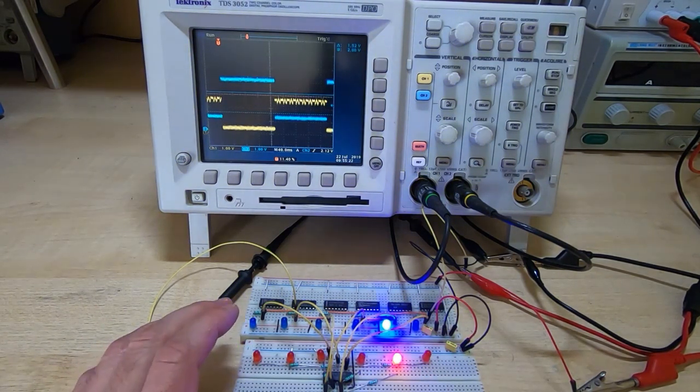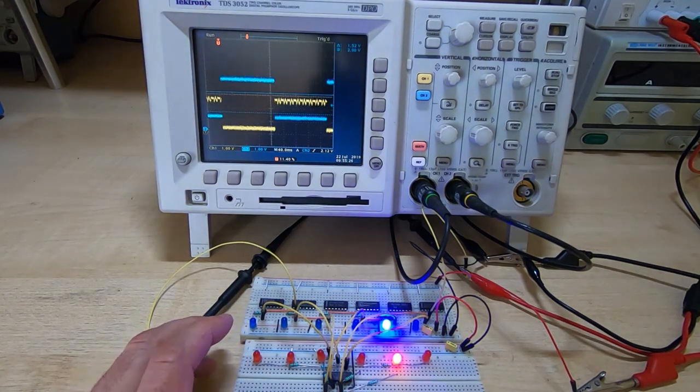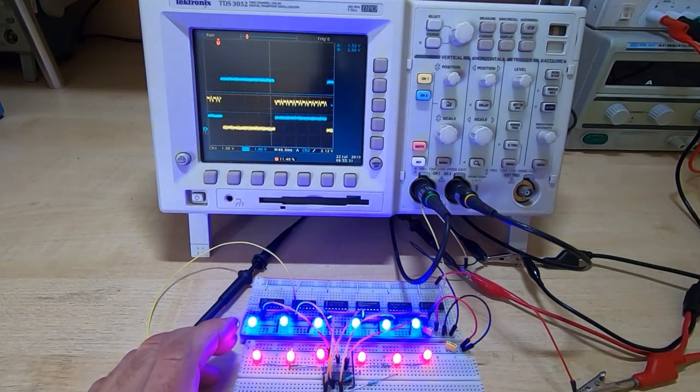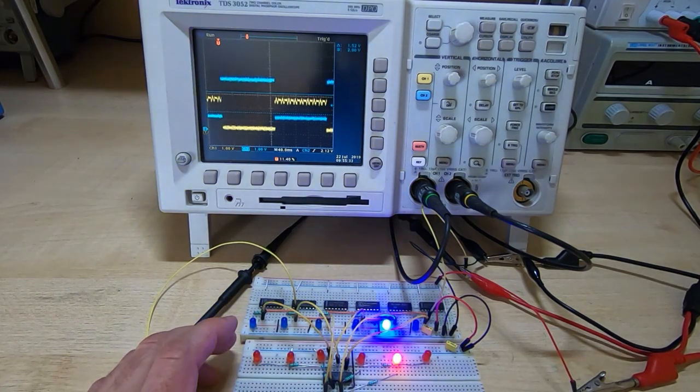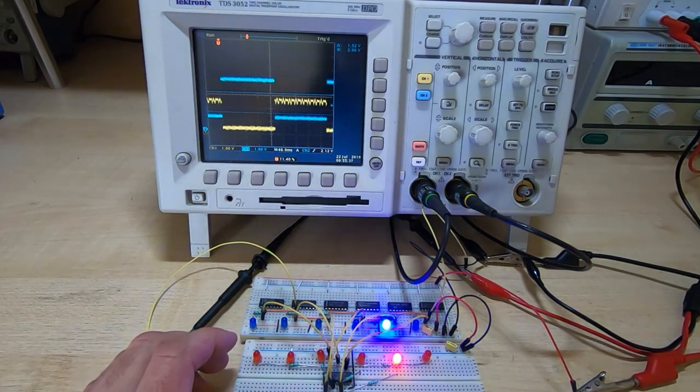And because a lot of the buses are common, a device in a board that seems to be working might be the one that's causing the issues in the other boards that seem to not be working. It can get very confusing, so it's really a case of trying to eliminate the problem by seeing what devices you have and what the signals are doing.